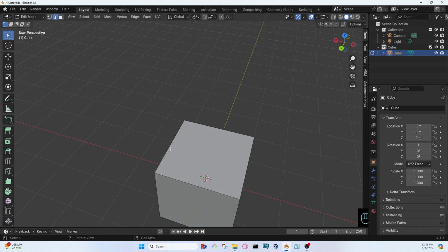If I select 3 edges and then go to face mode, it still doesn't select anything, because that was not enough to close that polygon, so it has no face to select. However, if you select a face and then you go to edge, you will see that all 4 are still selected, and then you go to vertice and you will see all 4 selected, because that had enough data to continue down the selection mode.